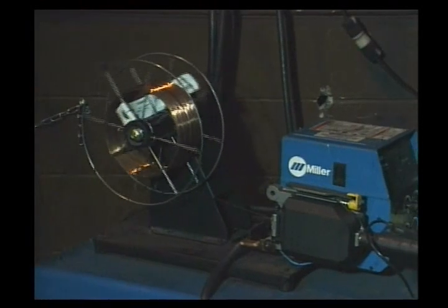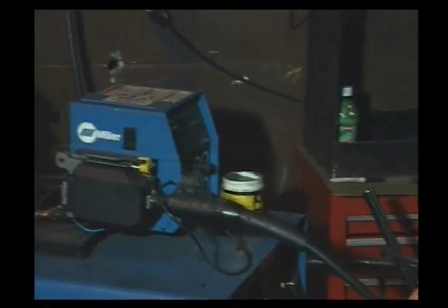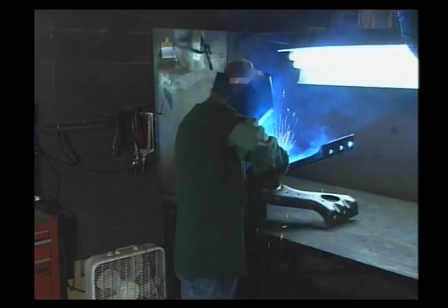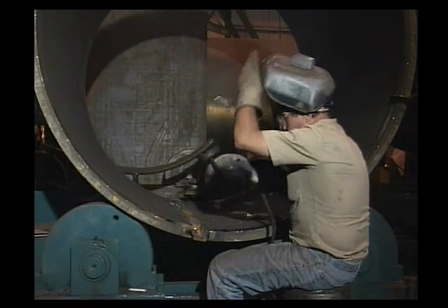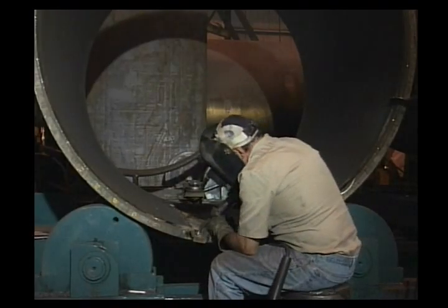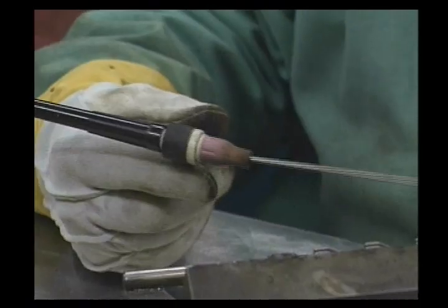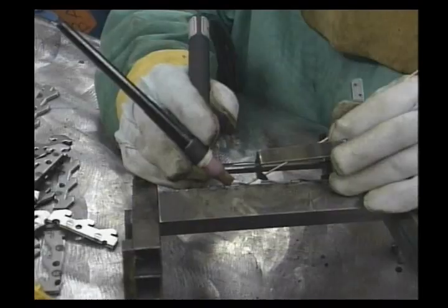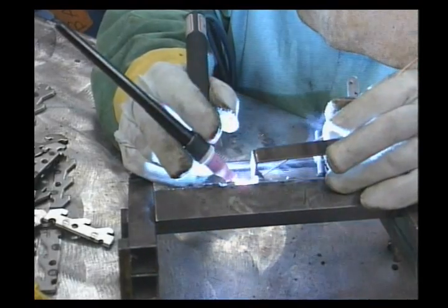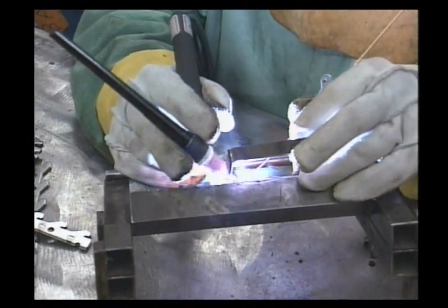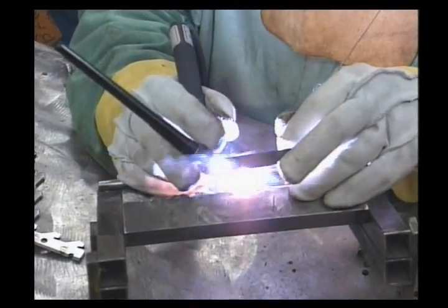The consumable electrode is usually wire or rod, and the current that sustains the arc also melts the electrode so that it supplies filler metal to the joint. The electrode may also produce a slag covering to protect the hot weld metal from oxidation. The most common non-consumable electrode is a tungsten rod, which carries the electric current. If a welding operation using a non-consumable electrode also requires a filler metal, it is supplied by a separate wire, rod, or consumable insert.